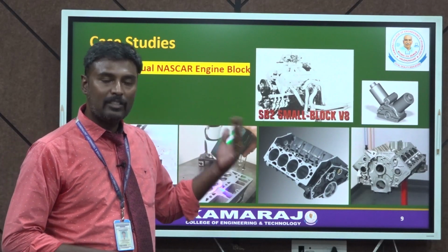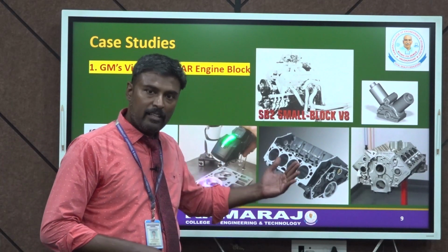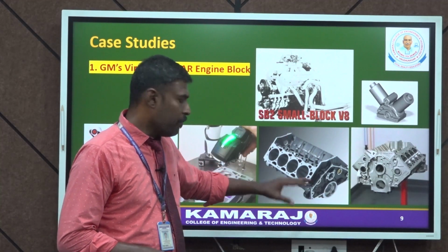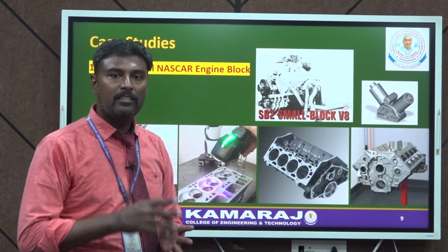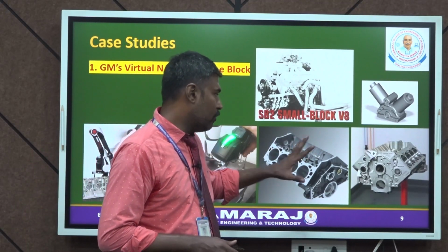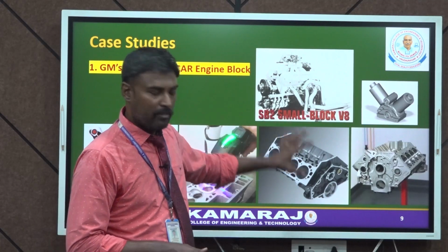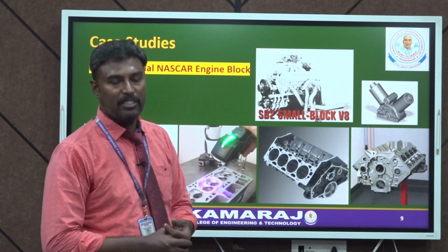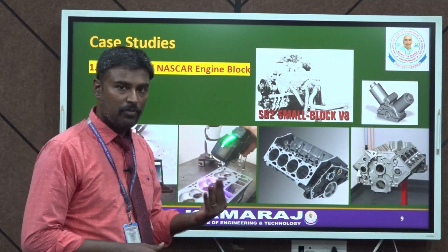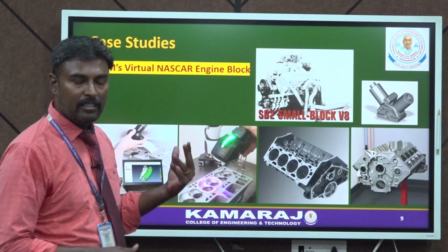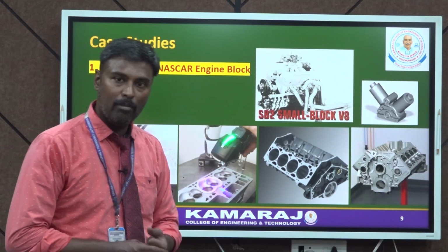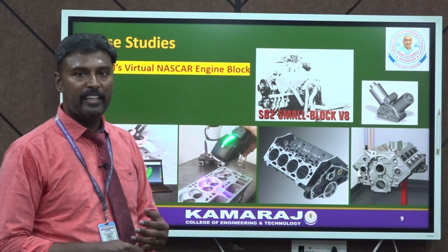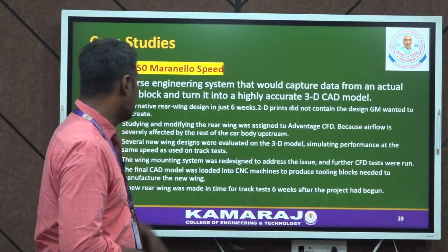It will take 4 to 6 months to grab all these point cloud data and refine it. Once refined, they have to verify it, and based on a tolerance of 0.03 inches they have to rework it. Once the final optimized design is confirmed, they manufacture this component using traditional CNC machines. Likewise, they successfully completed this General Motors SB2 engine block. This is one of the most important renovations in the history of reverse engineering in the automotive sector.